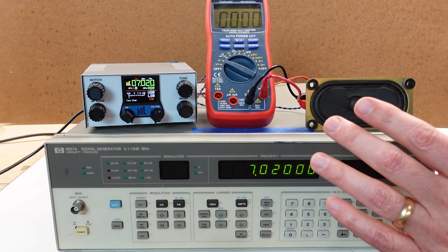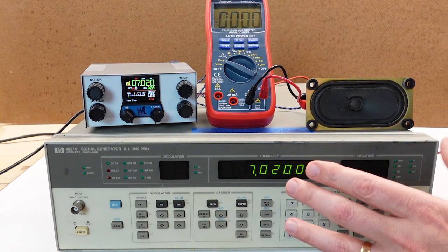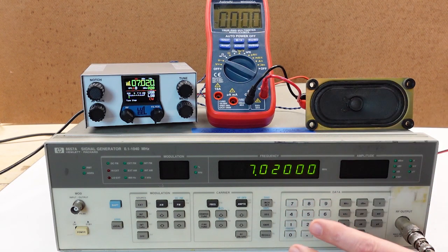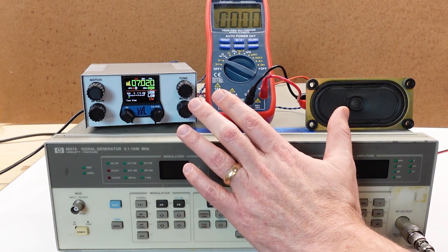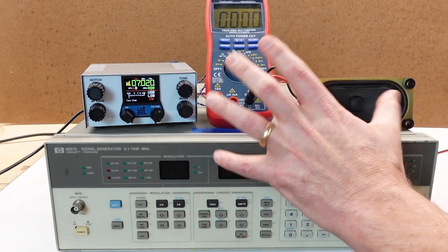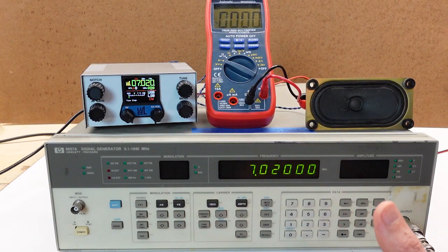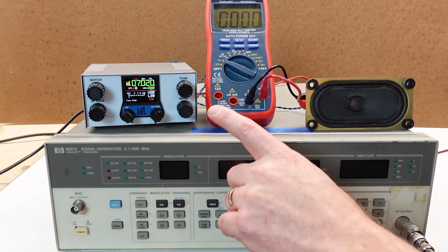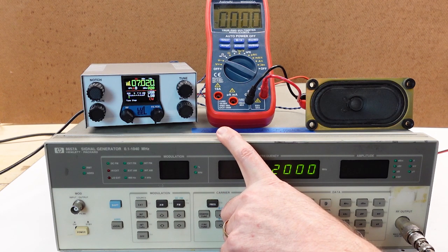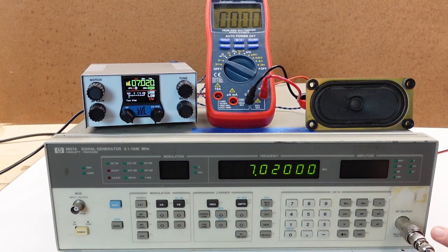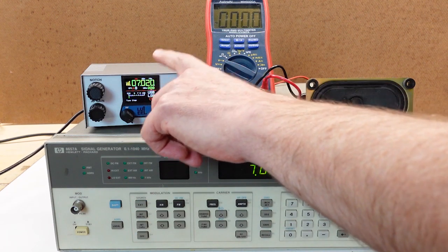So I have run this test to get the numbers off screen, and I had the equipment set up across my workbench. I've just stacked everything for the sake of the video so that it's easier to see, and just run a demo of how it works. So it starts with a signal generator, and I've got my big boy out, my HP 8657A. Now I do have a 20 dB inline attenuator before the cable goes up to the input of the receiver.